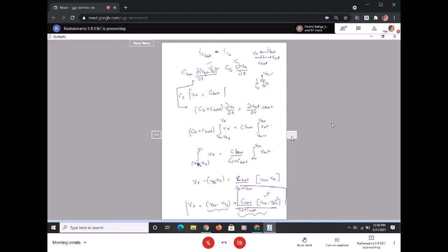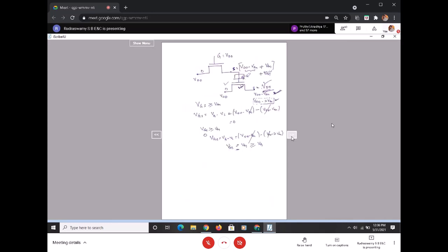Now I'll just go ahead with this. I'll use the same thing. So now I'll come from the previous Vx. Hope you people understood what exactly this is all about. I am just ensuring that whatever threshold voltage drop was there at the output, I am overcoming that by increasing the gate voltage. And that's what we mean by voltage bootstrapping.